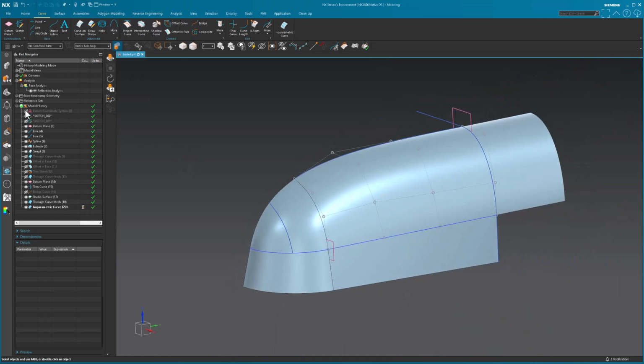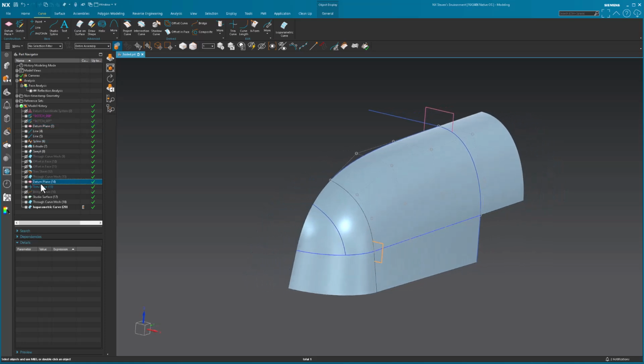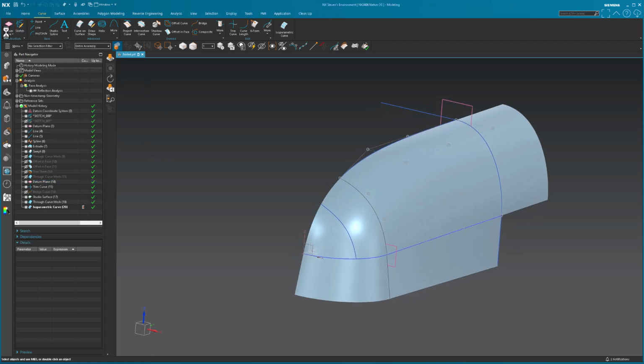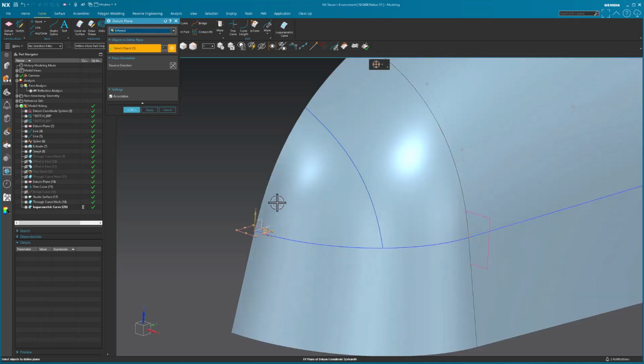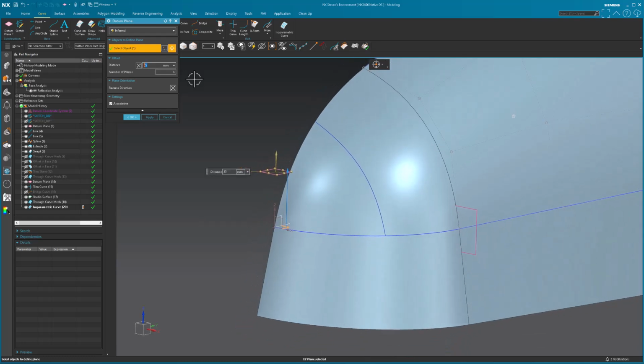and then let's see here. We had one. Go like this. Let me offset a datum. So back to the original point. Let me take this guy, offset that up 25.